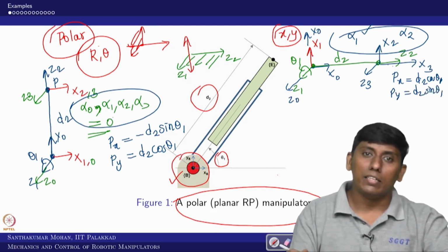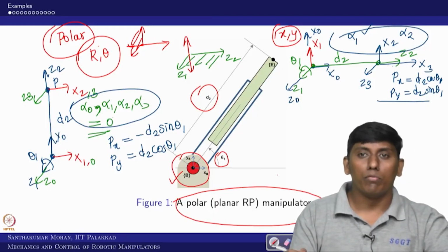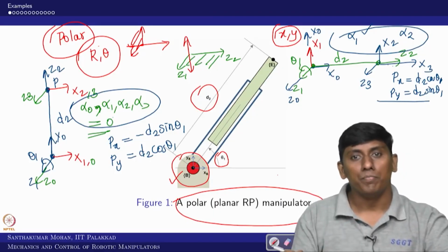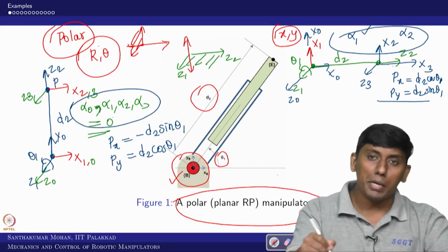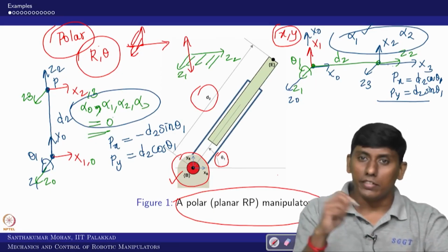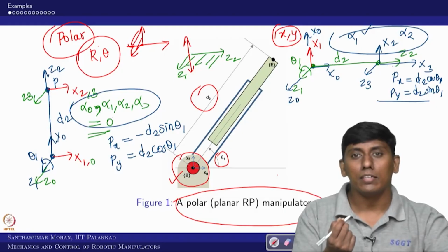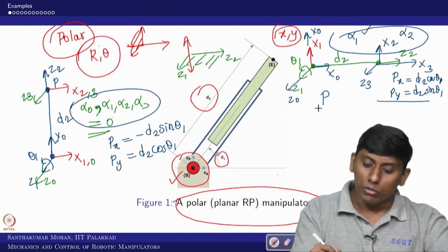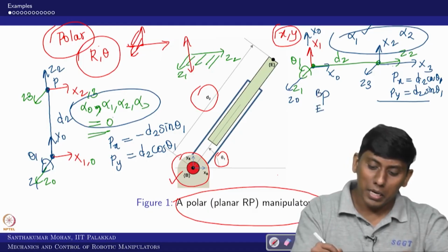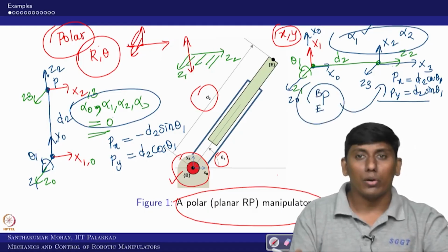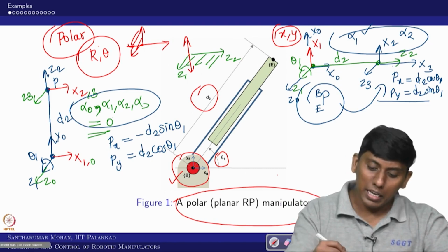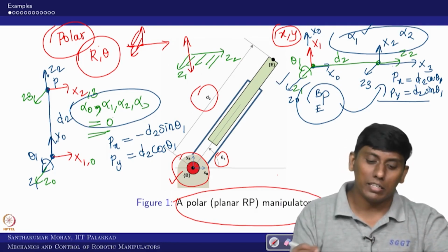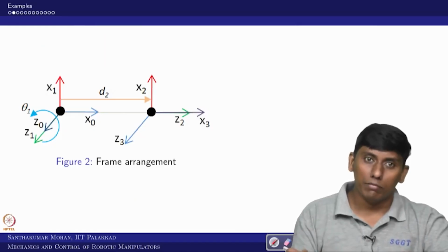So we can get this, but this is what you call forward kinematics, right. We will see how to do this formally. In the sense we will take this frame arrangement, get the DH parameters, substitute them into the arm matrices, and then multiply and finally get the end effector with respect to the base, and check whether it matches. For that I am taking this representation, because it is well suited for inverse kinematics.